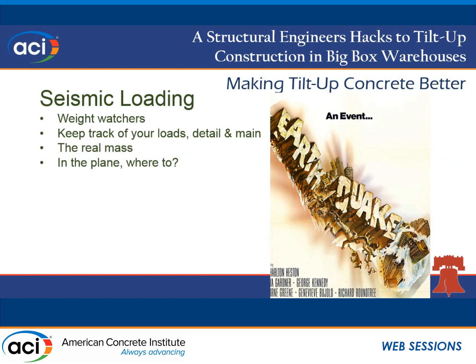Seismic. I'm sorry to say to all those in California, the rest of the country does have seismic too. We experience it, and in big boxes, you can have a relatively low acceleration and still be controlled just because your mass compared to the wind load exposure is so much. You're talking a 500 by 500 foot building with a 10 PSF mass. It doesn't take much acceleration for that much mass to get activated.